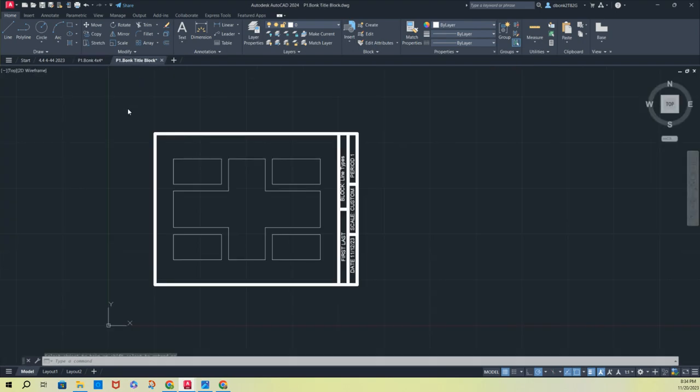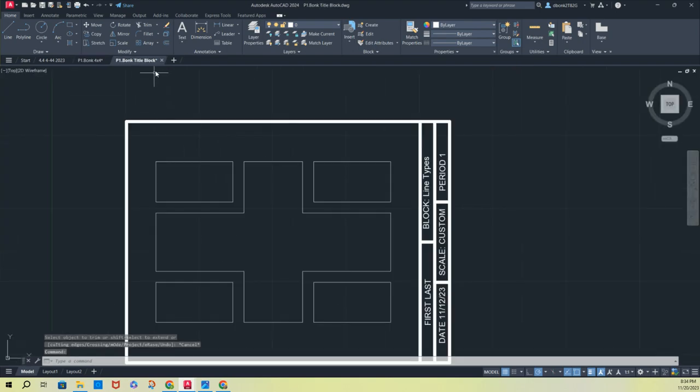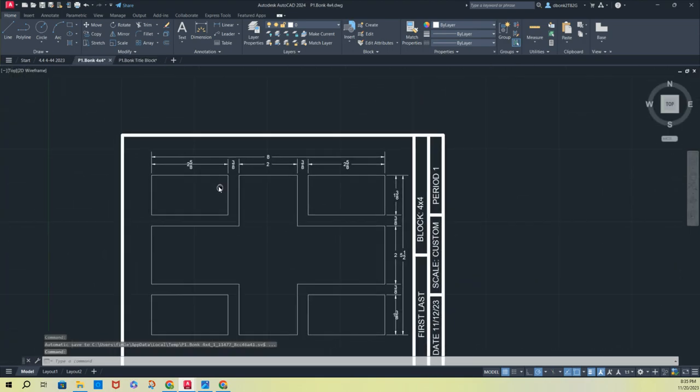So what that means is you're going to create an offset line using this line in your drawing. Click it 3 times, type in 3/8, then click it again, and then type in 1/4. So that's where the alignment of the two sets of measurements are going to go when we're doing our measurements here. I'm going to do it down here, outward 3/8, enter, and then offset that again, 1/4. All those are is placement markings. And when we're doing our measurements, we'll go over this in a little bit more detail.